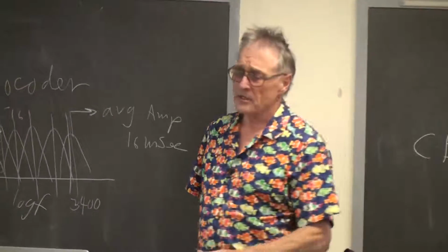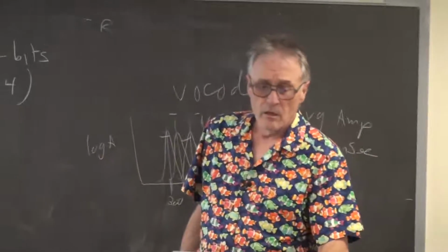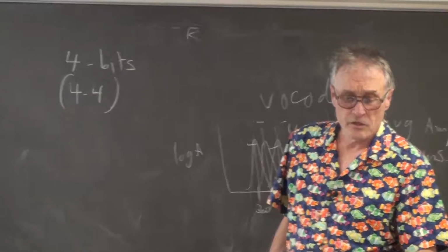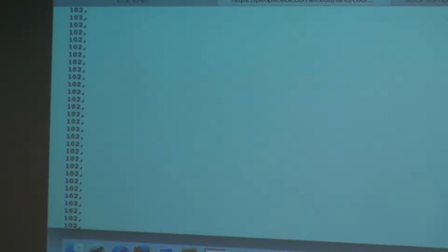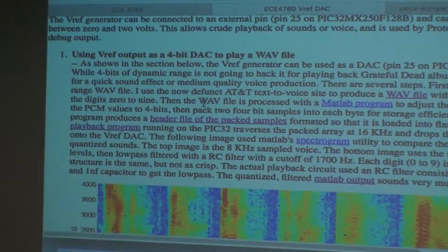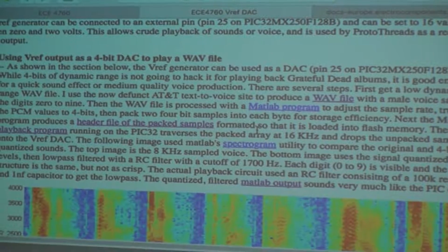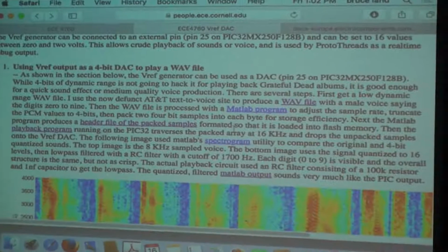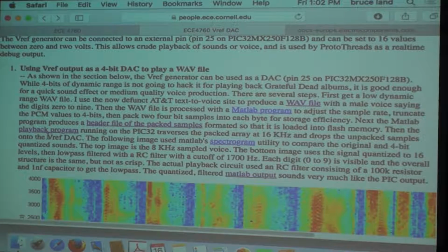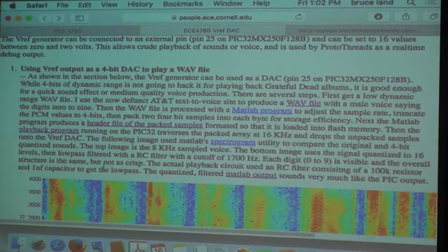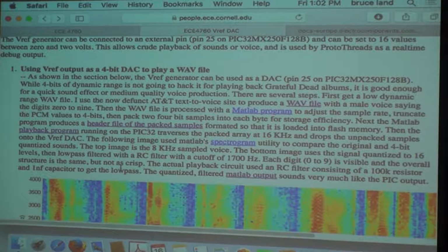But these represent each entry. Those are a lot of zeros there is what those are. Each entry represents two time steps, 2 4-bit samples of the amplitude waveform. When we want to play this back, we're going to traverse that.